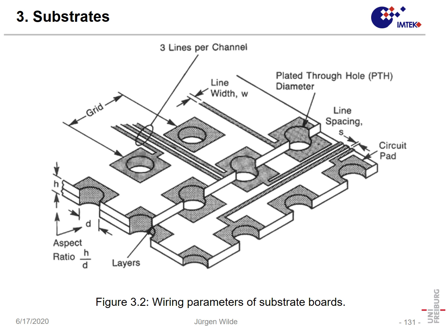What is important in a substrate? Of course, we must be able to mount our devices, and these devices can be mounted closer together or with a larger distance in between. On the other hand, the substrate itself must provide conductor lines, as we can see them here. And a typical substrate has several active layers of copper. Here we only see 2 layers which are active. There is a third one on the back side.